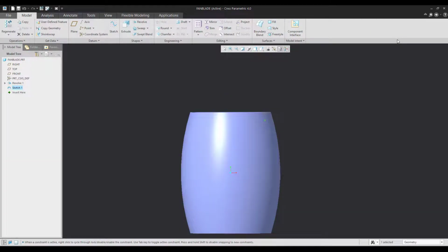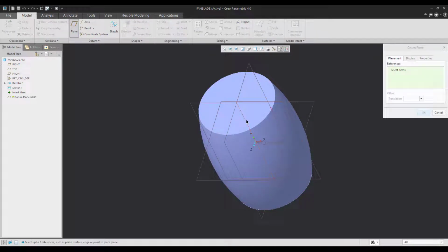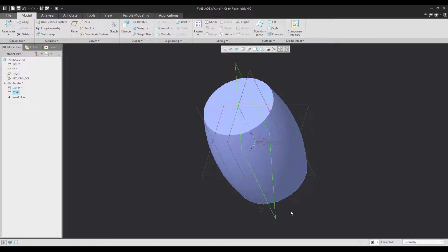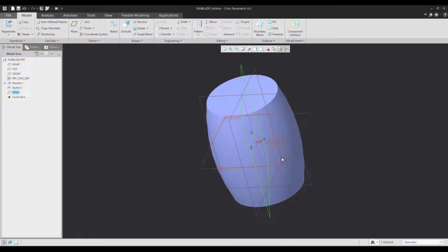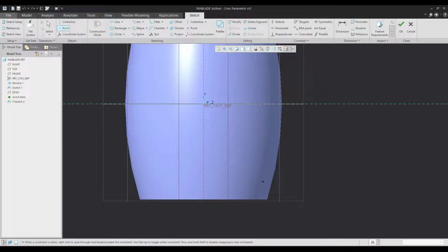Say OK. Now, if you can see the picture, the blade actually starts from here, crosses all over and ends over there. So we need to have a point over here as well at a certain angle. So let me assume that the angle is around 72 degrees. And I need to place a point here, so the curve starts from here and ends over here. So on this new plane, I am trying to create a sketch at the same distances whichever I have made the first point. That is, it actually states 2 mm from here and 8.5 from here.